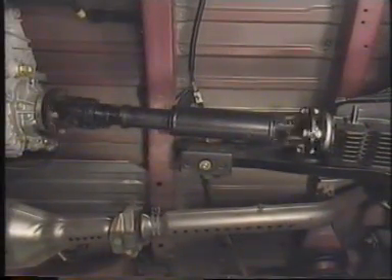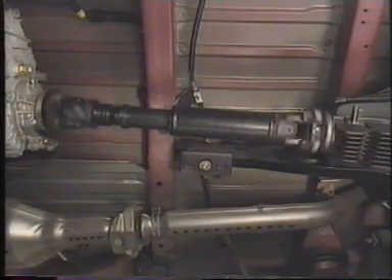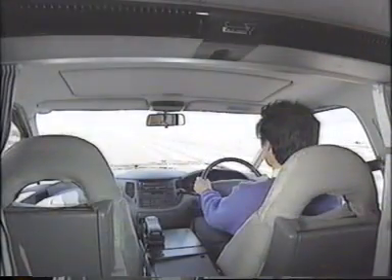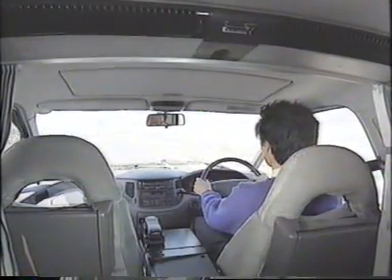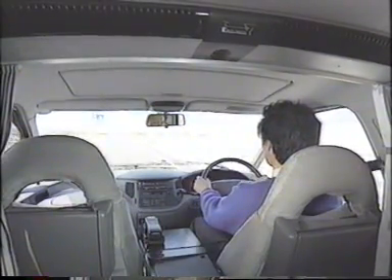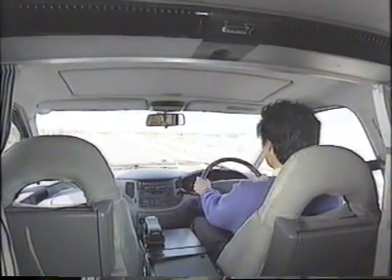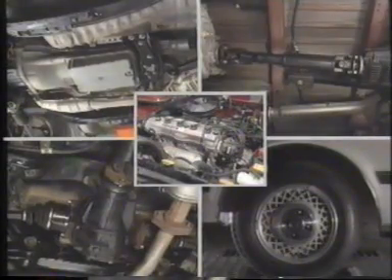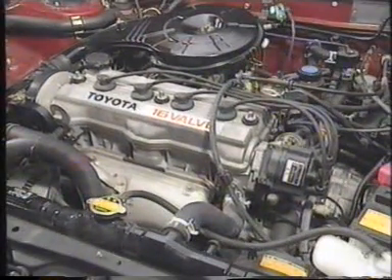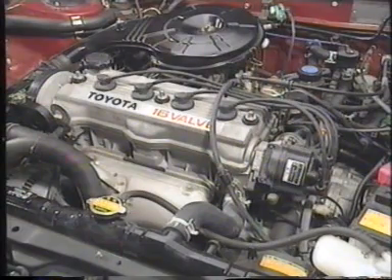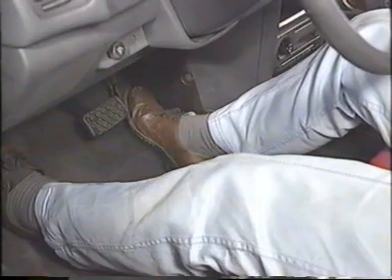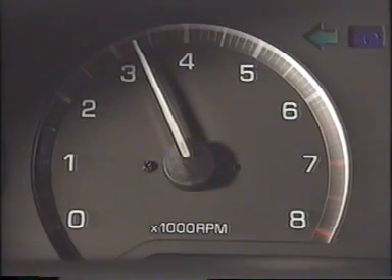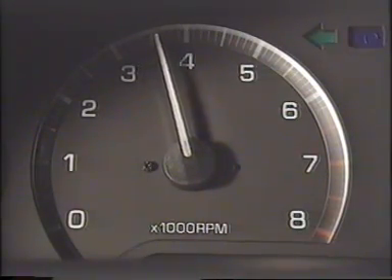An unbalanced propeller shaft also causes vibration each time it turns. This can cause a droning or humming noise called booming, as well as vibration when the car is running at a high speed. The engine, too, is a major source of vibrating force. The torque fluctuations due to combustion in the engine create a vibrating force. This may also cause booming.